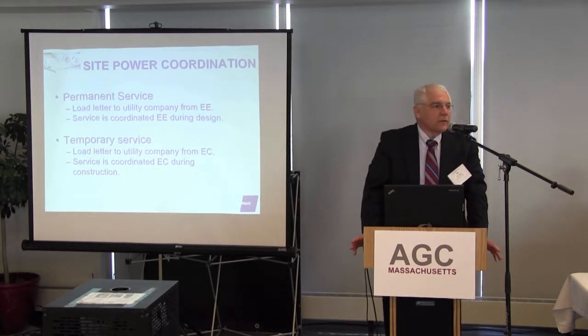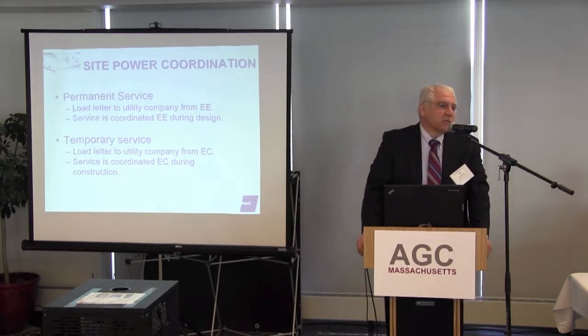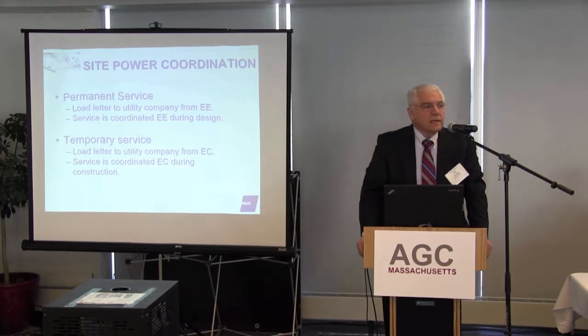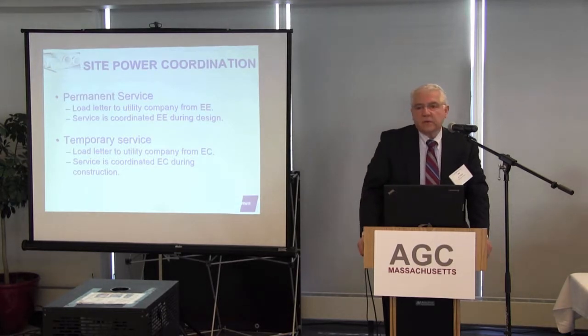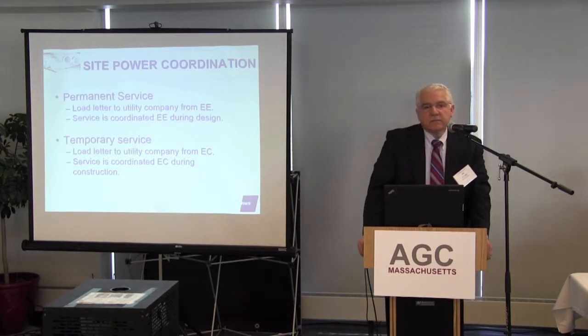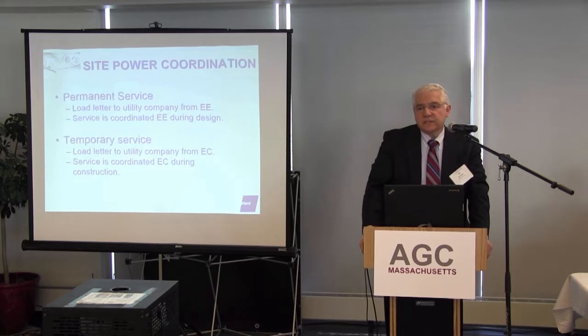Now we're doing a project right now at Seaport where there are 3 tower cranes on the site. Then they have the requirements for welding on the site, which is usually a 480 volt, 100 amp feed. You have the staging that you see traveling up and down the building, and that's usually a 100 amp feed, or 60 amp feed, depending on what they have.